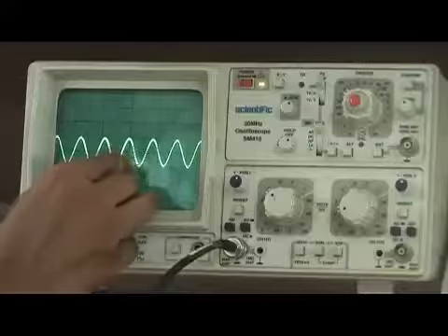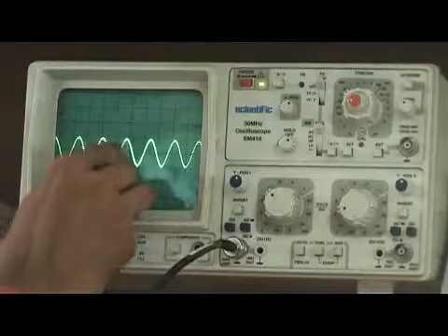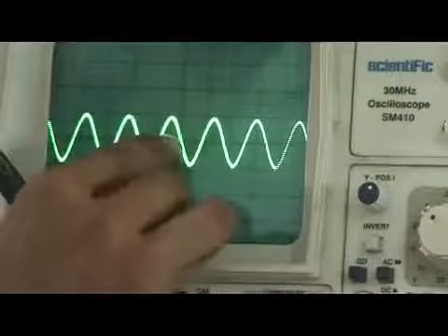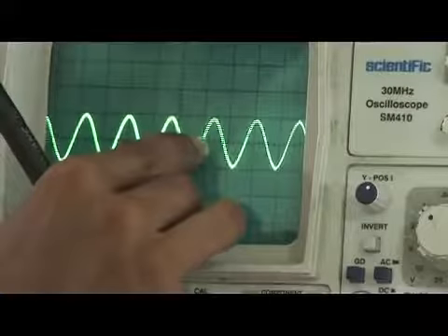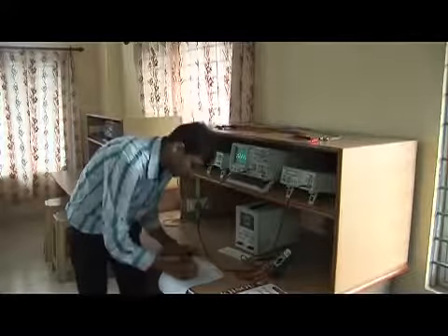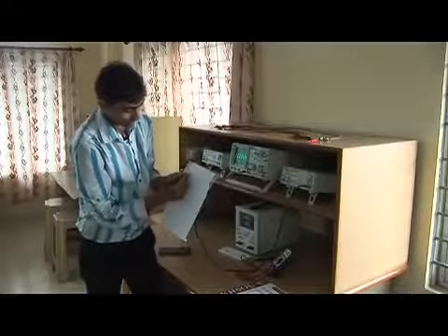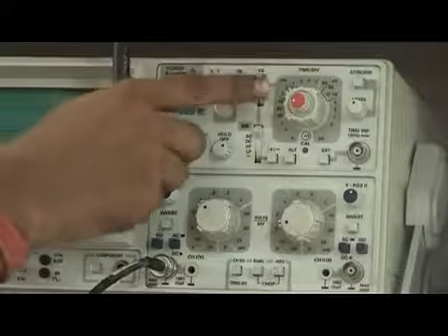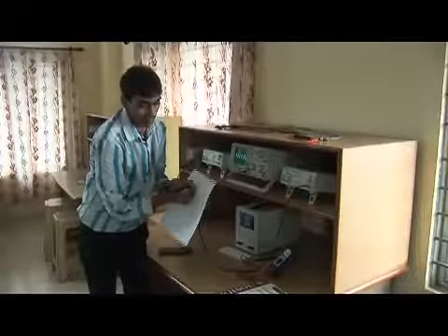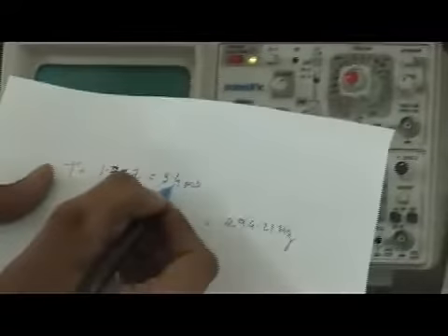So if I see what is the time taken by this cycle, we can put here. So this is one complete cycle. It is almost taking 1.7. If you count this scale from here, if you take this as one cycle, from this to this is around 1.2, 0.4, 0.6, 1, it's 1.7. So it is 1.7, you can say. Time period is 1.7, and you have to see the magnification of this time period. Right now you can see this is the knob. This knob is at 2. So we are using this into 2. So this 1.7 into 2 is giving us 3.4.